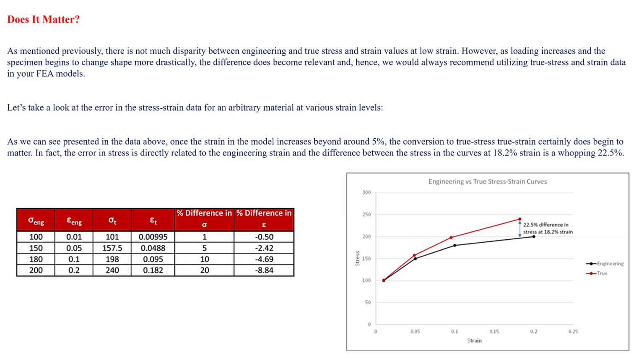This difference becomes relevant, and then we recommend utilizing the true stress strain data. If you look at the table at the bottom, when we cross the strain value of 5%, you can see the difference.